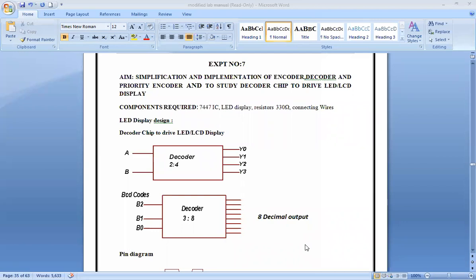The supply voltage, etc. Basically, it contains all the characteristics of your integrated circuit: what temperature is good for it to operate well, what is the maximum temperature we can operate at, what is the minimum temperature, how much voltage is to be given, and all of its properties. Some data sheets also involve a few graphs, and as you suggested, even the pin numbers are given.